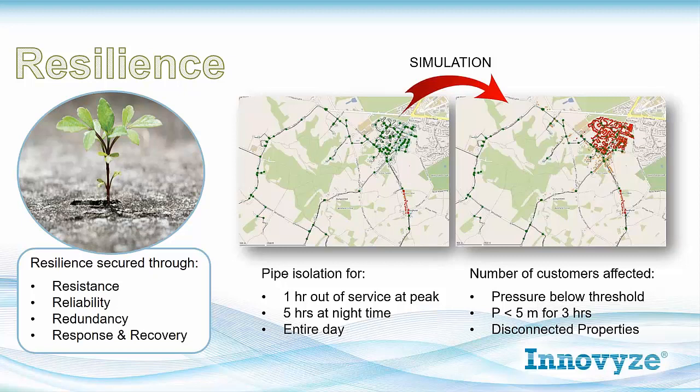What is worth mentioning now is that this kind of analysis needs to be performed using a hydraulic model and not by simply looking at GIS information. So just to make an example, here we have this town at the top of the screen that is fed by 3 mains. One of the 3 mains has been isolated to perform this critical link analysis.